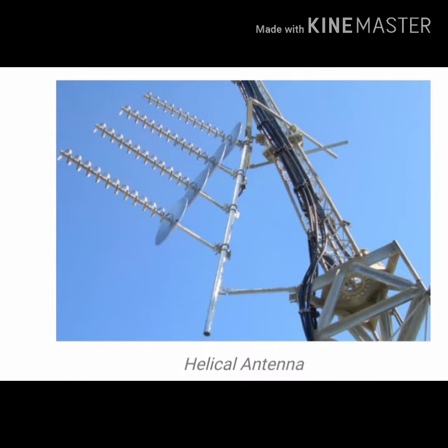Traveling wave antennas. Helical antennas. Helical antennas are also known as helix antennas. They have relatively simple structures with one, two, or more wires, each wound to form a helix, usually backed by a ground plane or shaped reflector and driven by an appropriate feed. The most common design is a single wire backed by the ground and fed with a coaxial line.